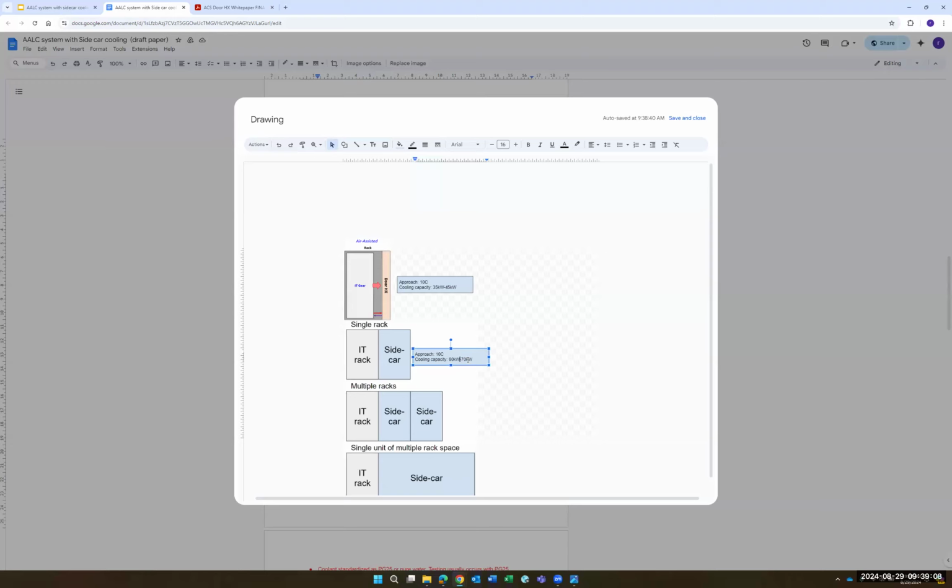Airflow that you can move per rack is how much airflow you can push into a single rack space in a data center. But that's limited by noise. That's limited by noise and also the airflow speed. Yes. Yeah, because it creates a lot of back pressure if you increase the speed, because your hot aisles are a certain width, like 2 feet or 3 feet or 4 feet, whatever it is. Now you are limited by that, and you have higher back pressure and you limit your airflow also.